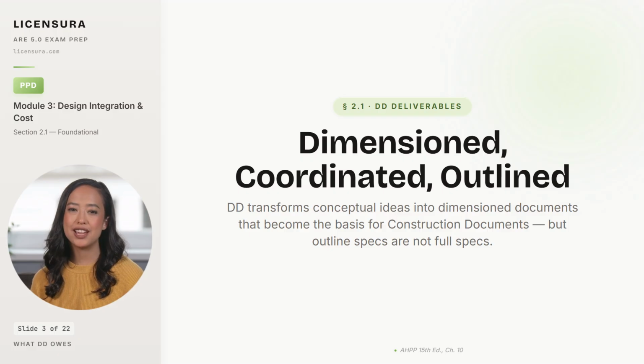That word outline is doing a lot of work in that list. Outline specs identify the major products and the performance criteria, but they do not yet contain the administrative procedures, the installation methods, or the section-by-section detail that contractors actually build from. Treating an outline spec as a complete spec is one of the most common traps the exam will set, because it is one of the most common errors in real practice.